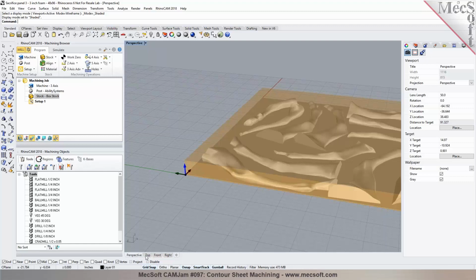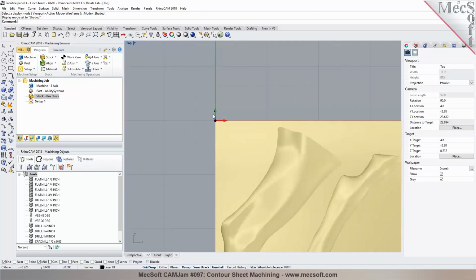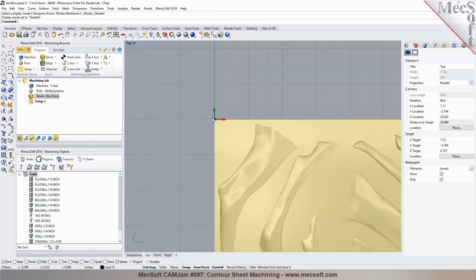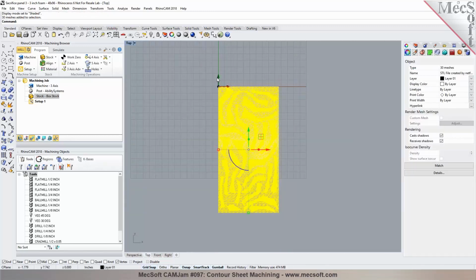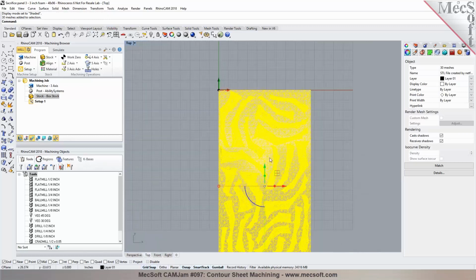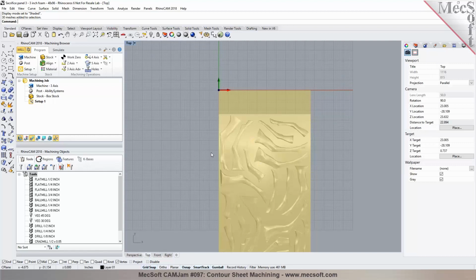Okay, we can certainly do that. So let's go back in here. And you said this corner has to be at -12, is that correct? Correct. Okay, so you could do a transform move in Rhino to change the position of it. So I can basically select everything in here, and I could move this in Y by -12. I can use the graphical manipulator in here, and I can type in -12 for the Y. So it basically shifts the part down by 12 inches.